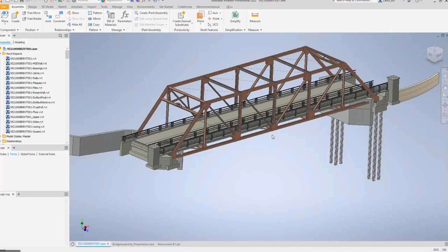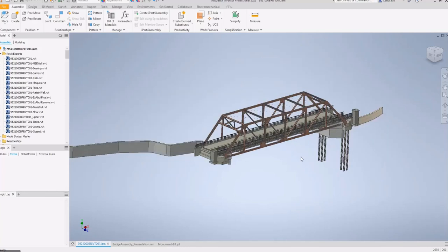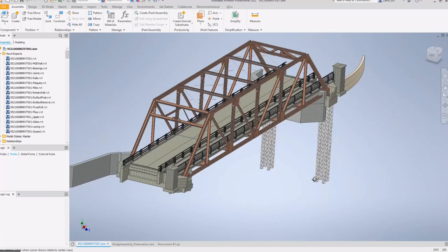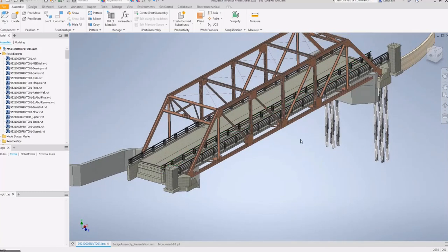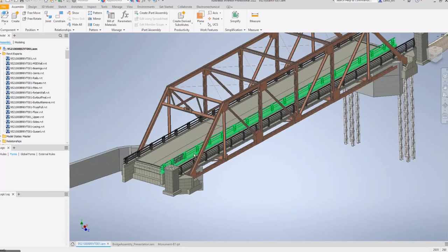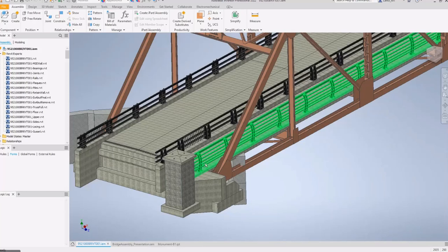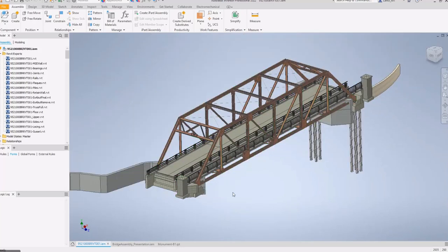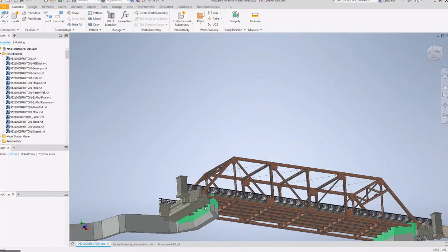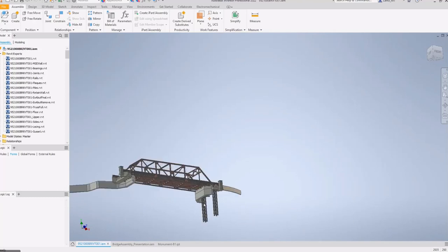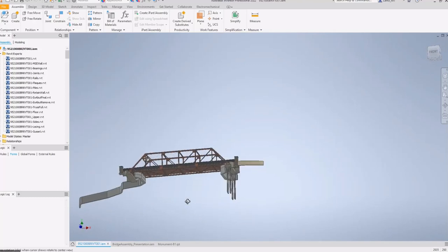I'm using this truss bridge that we're working on. It's a little single lane truss and the sidewalk. I wanted to go through a few of the components, first, possibly the level of detail. You'll see a new curved railing that we're looking at. We have a spread footing on one end. The side of the river is solid rock, and so a spread footing is what we have. And then on the other side of the river, interestingly enough, is very poor soil, and so we're building out a deep foundation on that end.